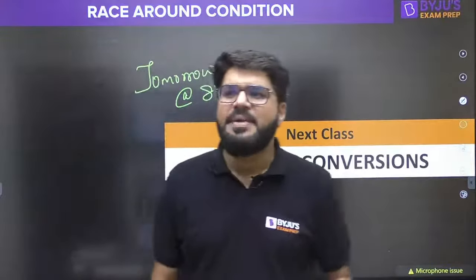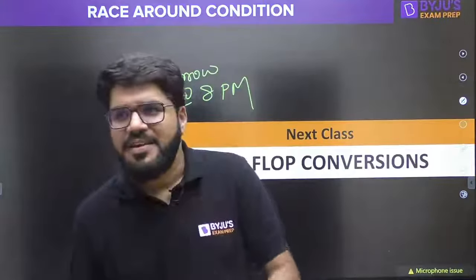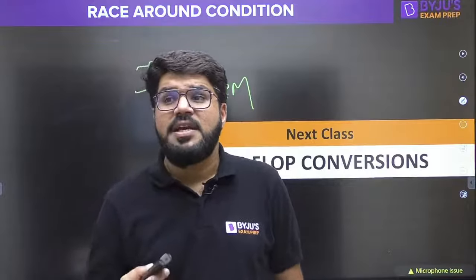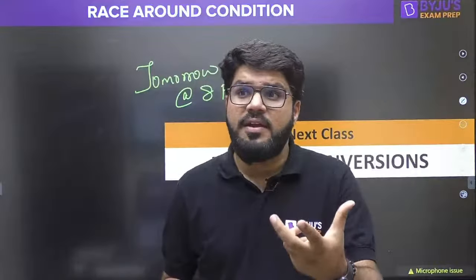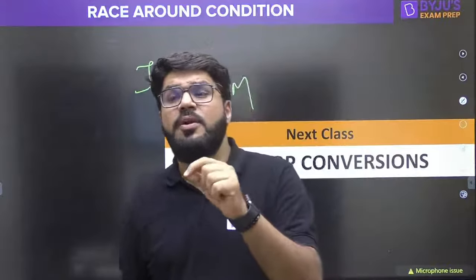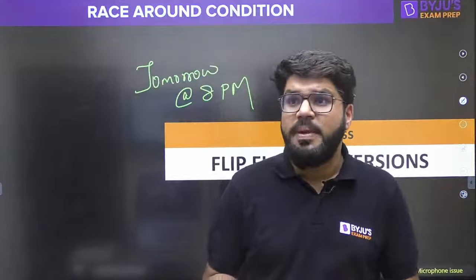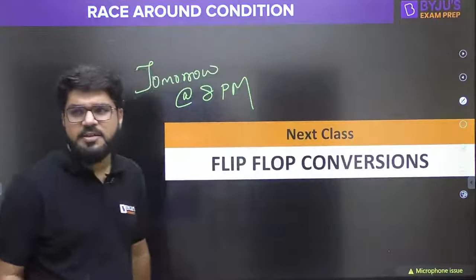Representation is not the working, basically. Representation is just a very irrelevant thing, Sugrita, to mention here. The working is what matters: latches respond to the level of the clock, they are level triggered devices. A flip-flop responds only to the edge of the clock, the transition of the clock. It is an edge triggered device. So the main thing is their functionality, their mode of operation. That is the main differentiation between them.